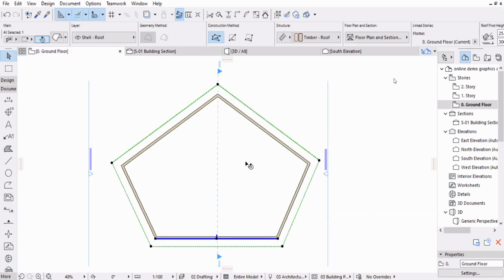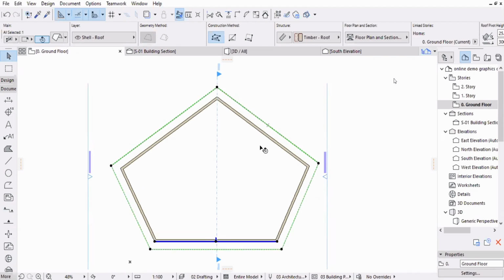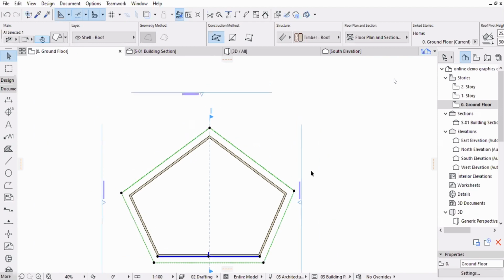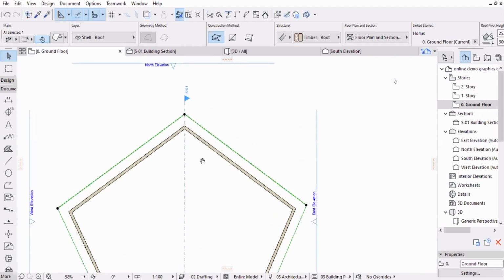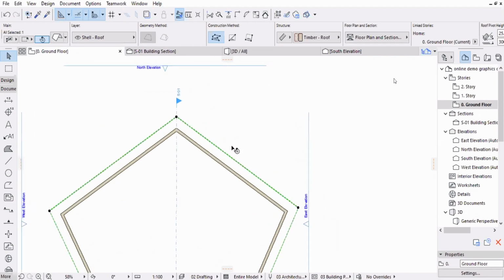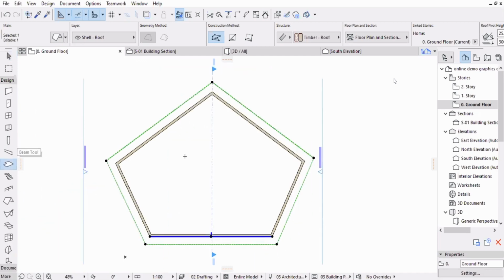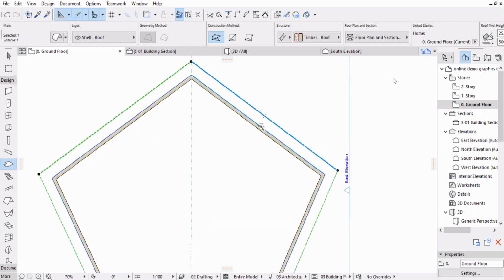For example, I want to increase this hatch. I have a veranda here, for example. I have a slightly larger area. You have not drawn the slab. So let me just draw a slab using the magic wand first. Go to the slab tool and use your magic wand, the space bar, and just draw it. You can use the outline or the overhang also here. I'll use this wall. It has drawn the slab.